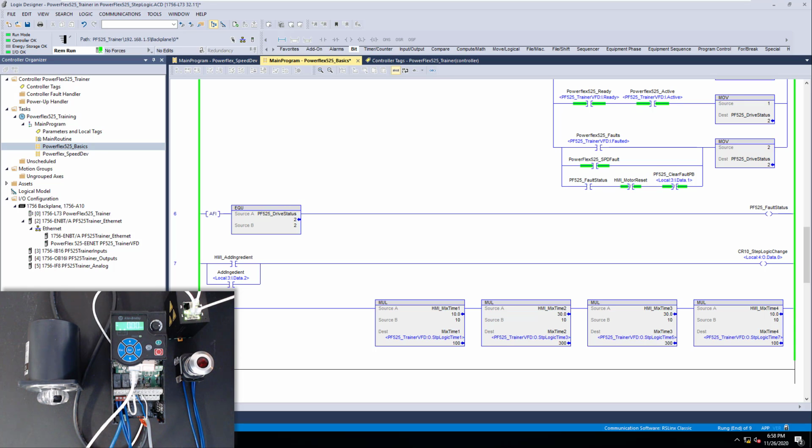Now, at this point in time, the operator will be putting the next ingredient into the actual batch, right? So that as soon as they got done, they put the last ingredient in and they said, okay, well, now I want to go ahead and do another mix. They push the button, they start the mix. You can easily see that it starts. So this is the way you would actually use step logic, right? And this is a good use case. I'm not saying that this is only for batching, but I'm saying this is a good use case for batching, right?